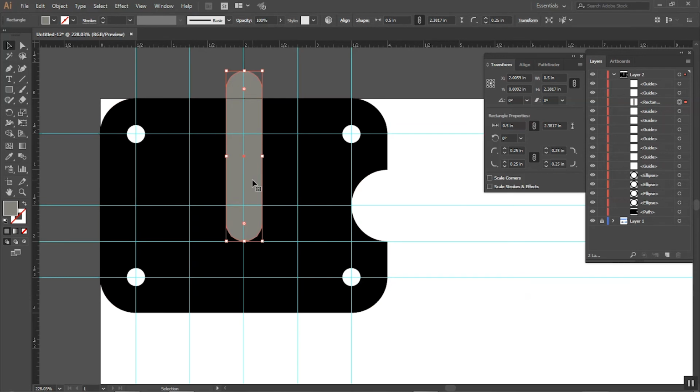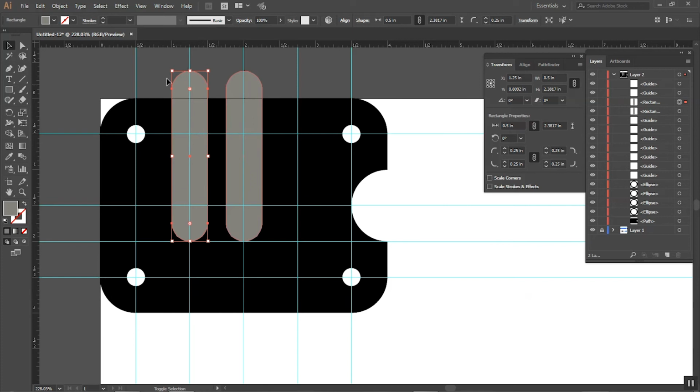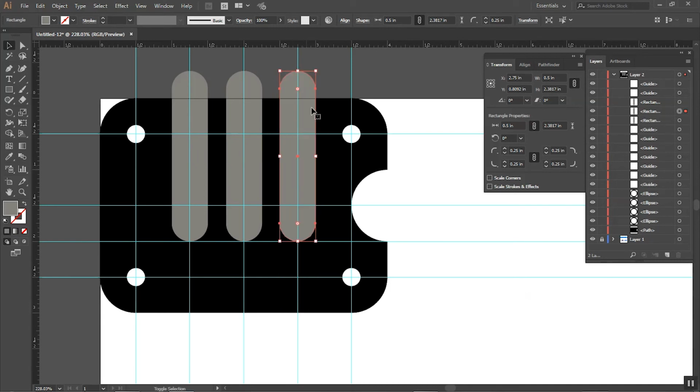So selecting these pockets again, if I've got the selection tool, if I hold down Alt, we've done this before, and move it, it's now duplicating that element, and you can see it's intersecting there. I'm holding down Shift, so it's a copy that's aligned straight, and then I'll do the same the opposite way, holding down Alt and dragging, and then if I hold down Shift, it will be aligned, and it says intersect with my guide.